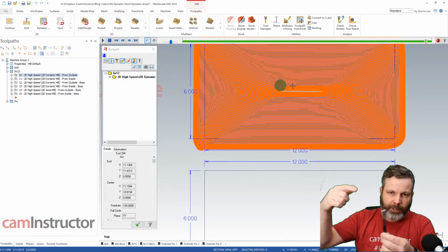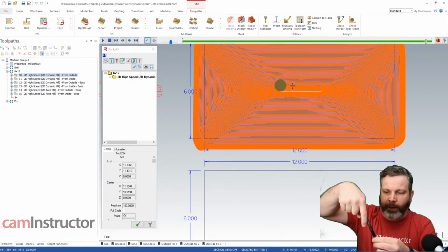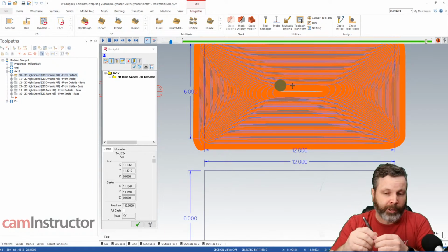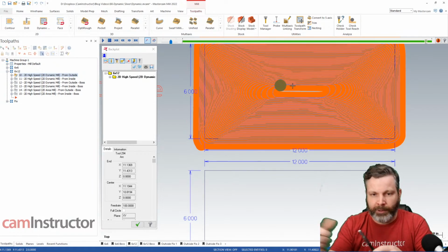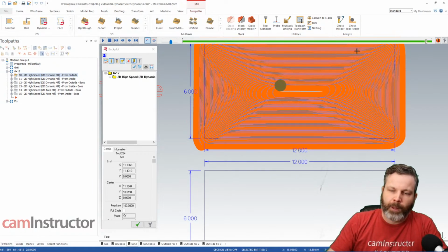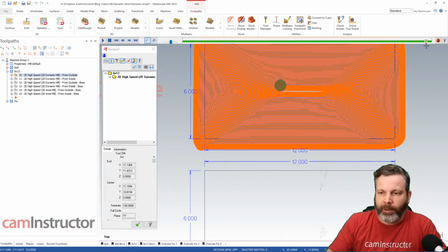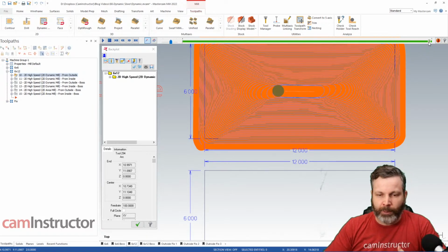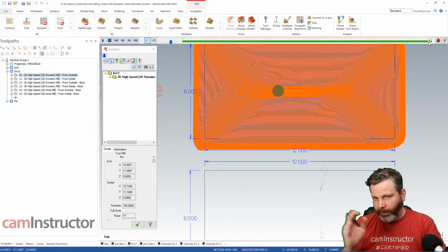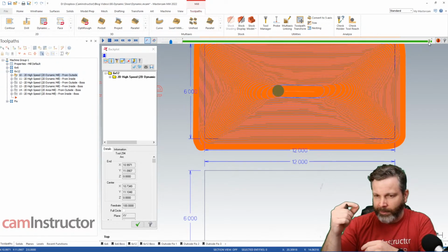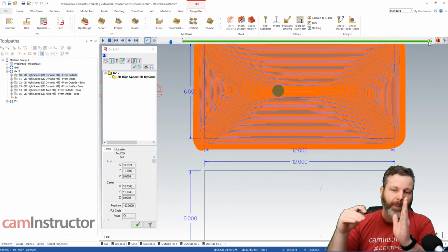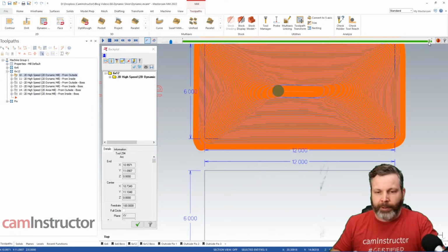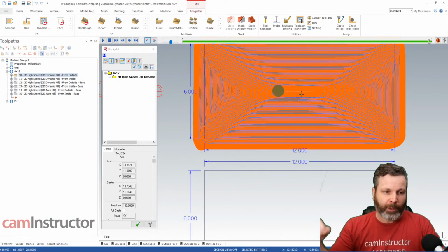That's not a big deal until you come back around the other side, and all of a sudden this piece that's tipped over, that you would have engaged 10% of your cutter into, is now engaging 30, 40, 50% of material because it's deflected over. That unexpected load on your cutter leads, obviously, to bad things happening. When you're pushing a tool at its maximum, right on the boundary of breaking versus not breaking, and that's relative to that 10% step over, if you're now getting into a cut that's 20% step over, things are going to go bad. Things are going to break. So this is the problem that can come up with Dynamic Mill.